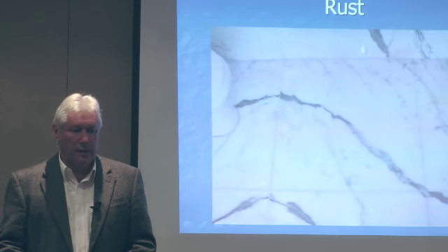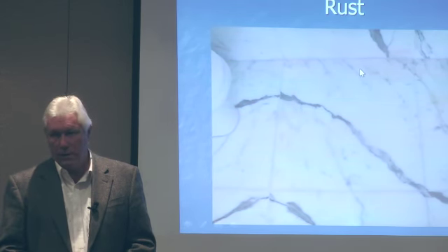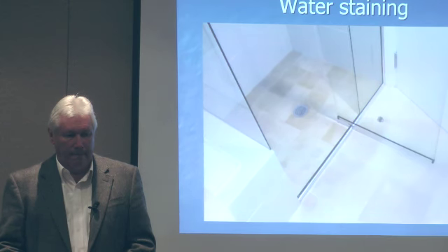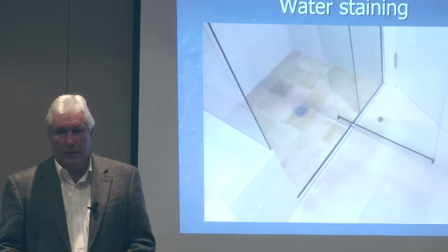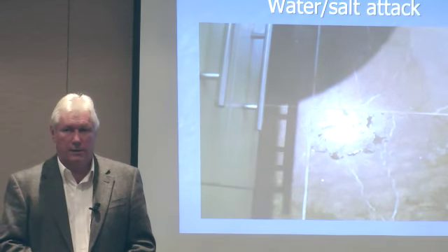So knowing a bit about the stone, sealing the back of those tiles completely with a water-based epoxy is likely to give you some protection against that kind of effect. Once again, there's some water staining that's going out past the shower because of the failure to incorporate a proper working water stop. Even if there was a water stop there, chances are the inside of the shower would have gone a darker colour than the outside. So knowing your water absorption of your stone is important.